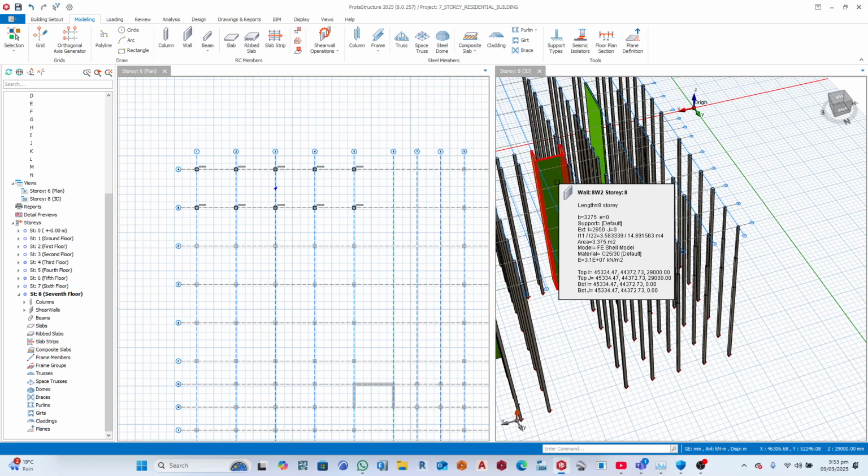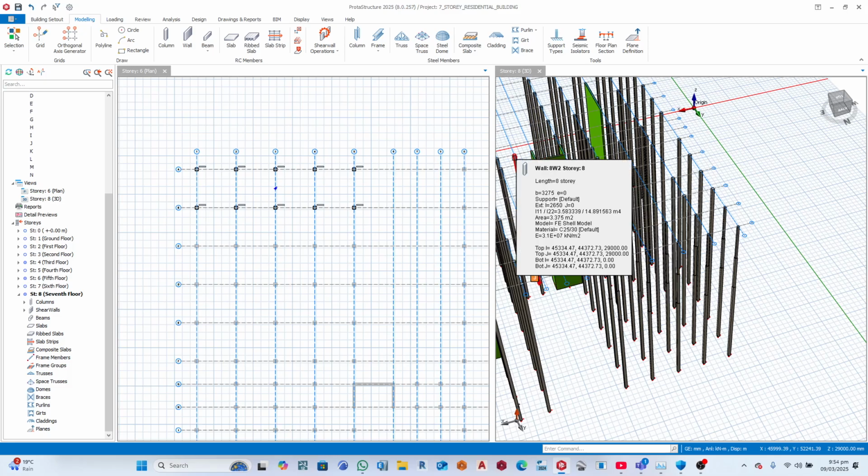So as we design also as structural engineers, we're supposed to design for redundancy, where we say, in an event that this column fails, the whole structure must not come down. Or if the column continues all the way to the basement and there's a basement parking, if a car accidentally hits that column and it fails, the whole structure must not come down.